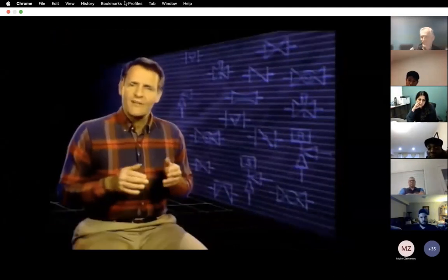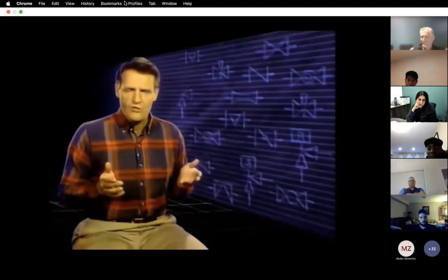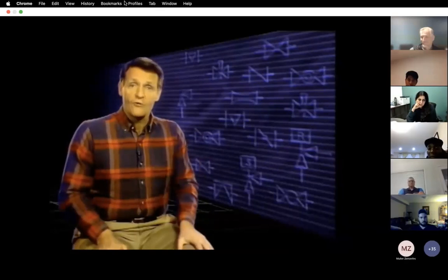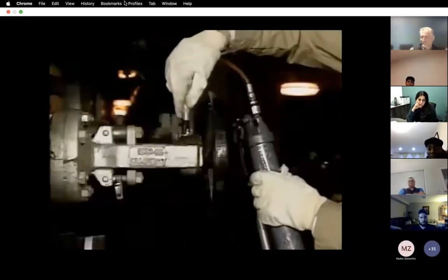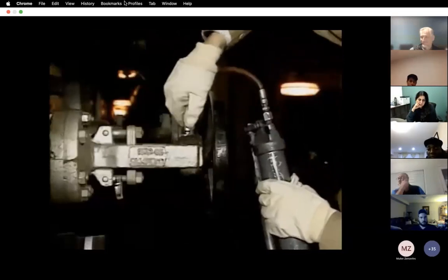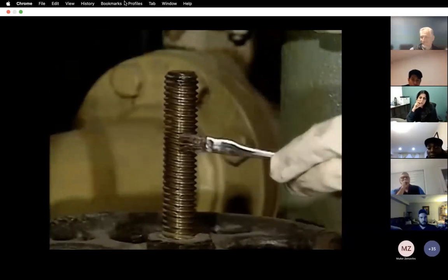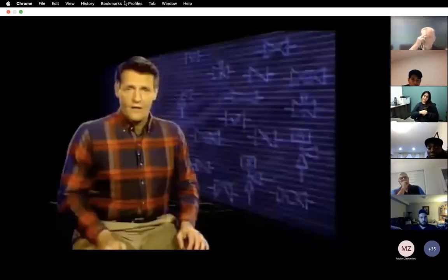Valves need lubrication to prevent components from wearing during operation. Each type of valve may require a different type of lubricant or method to apply the lubricant. For example, some valves have grease fittings and require the use of a grease gun to lubricate them, while other valves may have the lubricant applied directly to a component, such as this valve stem.